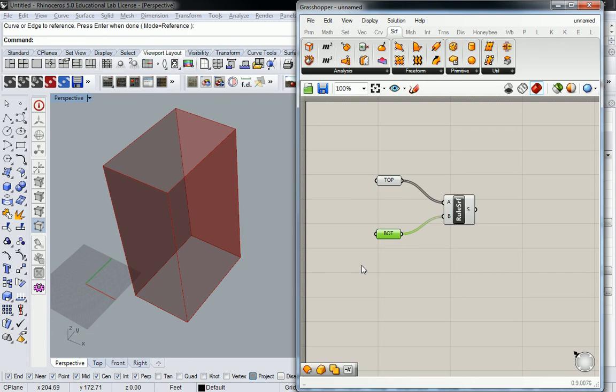Okay, so anytime, I'll also say this, guys, on the subject of those curves, or the edges being really oddly rounded or truncated, as long as the actual edges that you see are correct, generally the geometry will be correct, okay? So if I went back and re-referenced that and baked it, it would still bake out correct. It's just a graphic issue that Grasshopper sometimes has with poly curves, polylines, stuff like that, or really complex geometry.